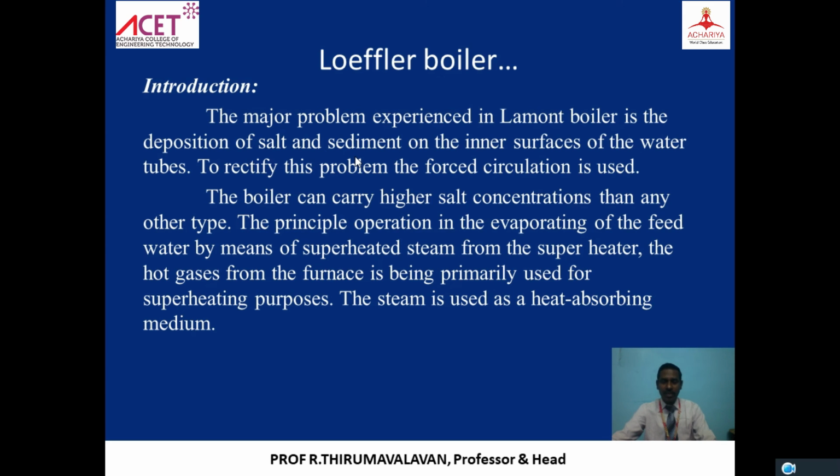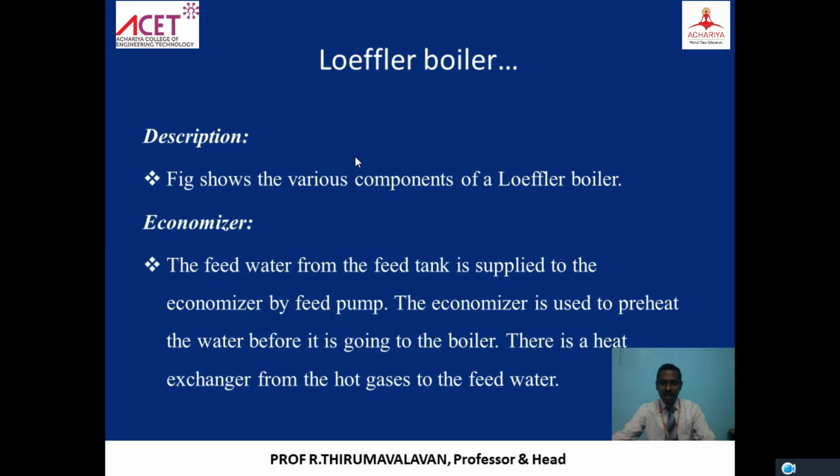The other parts, if we see them, start with the economizer. The feed water from the feed tank is supplied to the economizer by the feed pump. The economizer is used to preheat the water. Air preheater, water preheater. The economizer is the water preheater. It is a heat exchanger, also a type of heat exchanger which takes the heat from the exhaust flue gases.